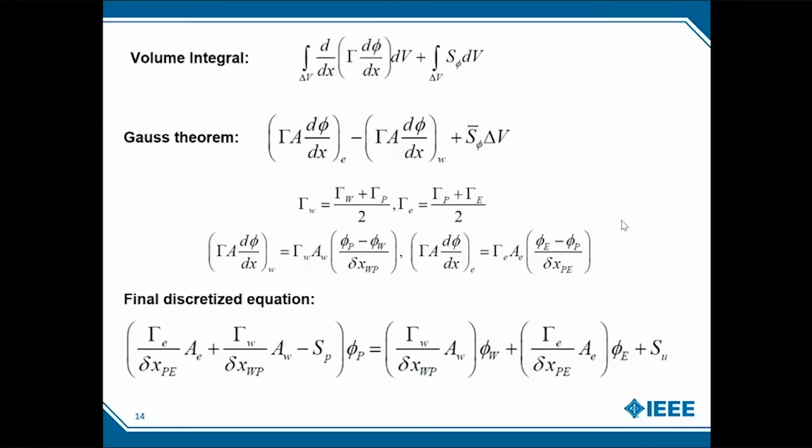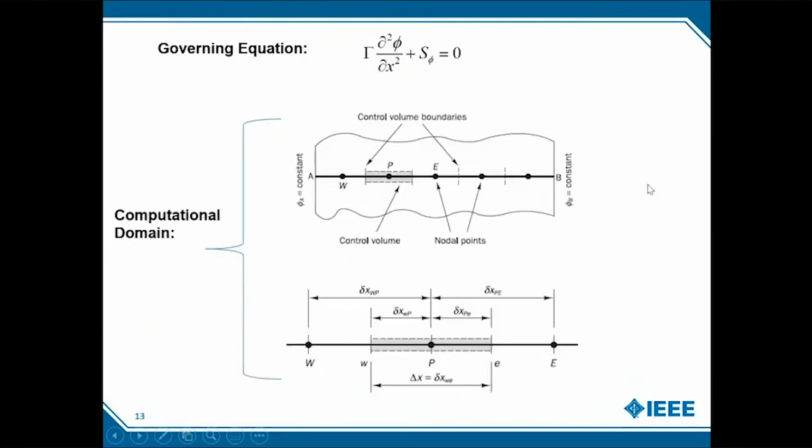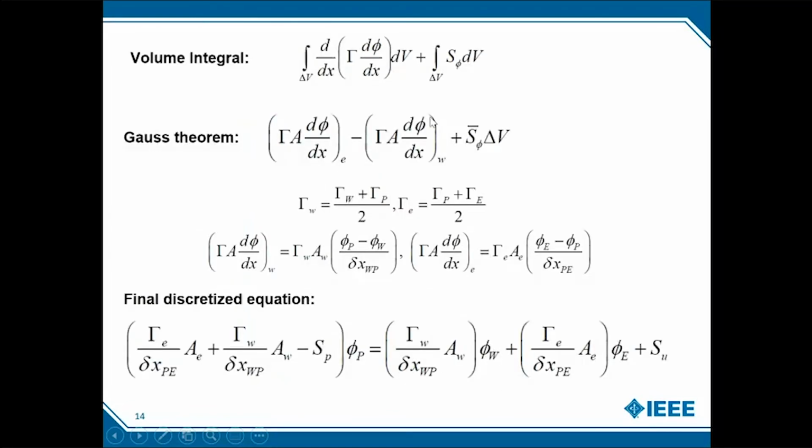Over here we have two faces for each particular node: the west face and the east face. The way we accounted for them was by summing them up and applying the appropriate sign based on the surface normal. So suppose you have a 3D mesh in which the cell has, say, 8 faces. You'll have 8 such terms.